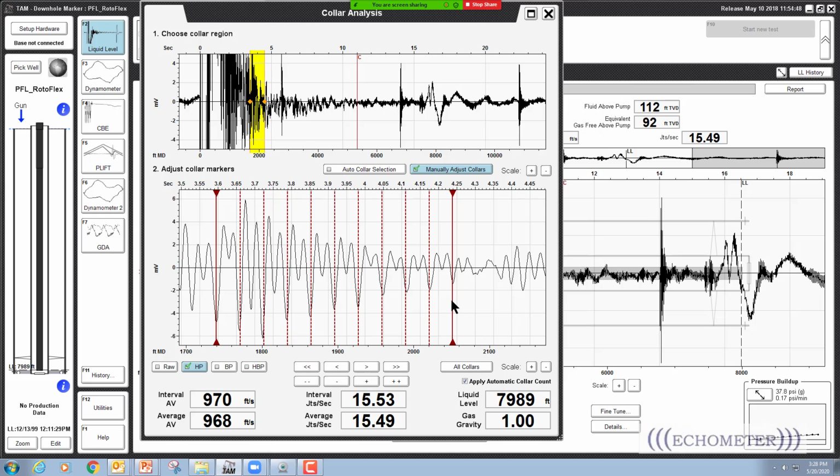Yes. Normally we don't really recommend putting more than 1,000 pounds differential pressure to make a shot. We don't use more than 1,000 pounds differential pressure for the very high pressure gas gun, and that's not bad practice to carry down to the 5,000 psi gas gun, even the compact gas gun, because more pressure means a bigger shot, but more pressure is more energy, and it could cause some kind of a problem, more wear with the O-ring, more potential for something not to work quite right.